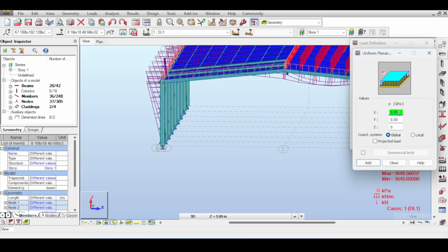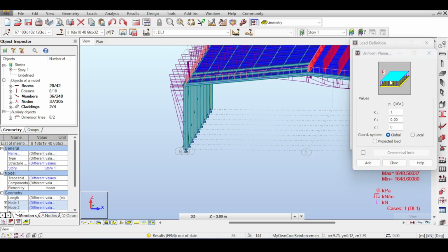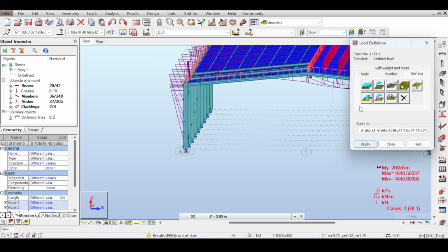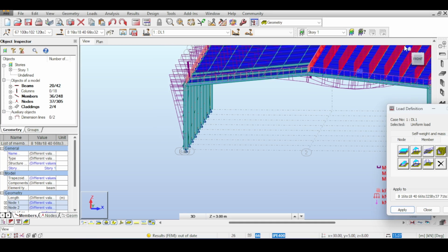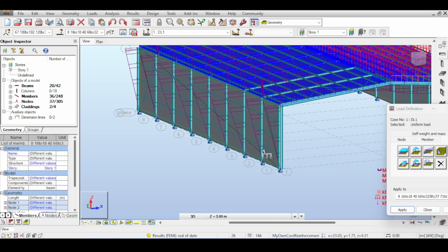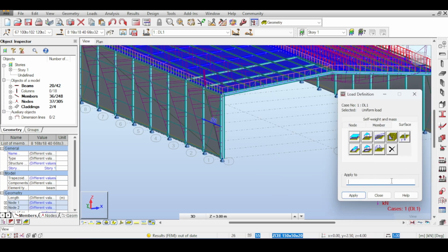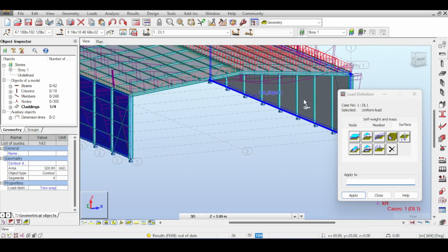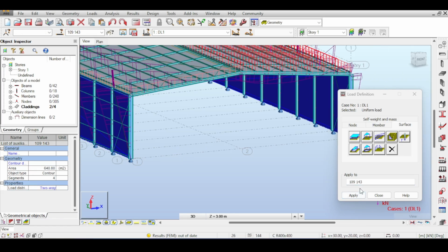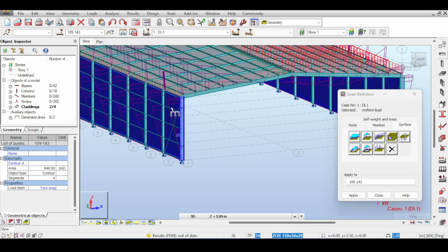This is just a dummy force. I'm just testing things. And I do this because I don't want to get any bad surprises at the end. I suggest that you do the same thing when you analyze structures: you should have a dummy force ready to apply on your structure to make sure that it behaves as it's supposed to. So now I have my forces.